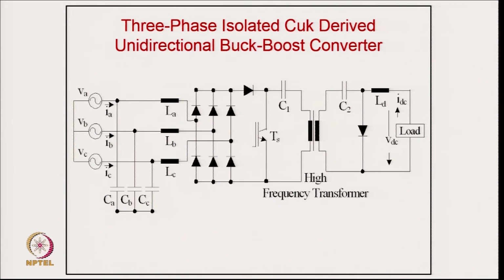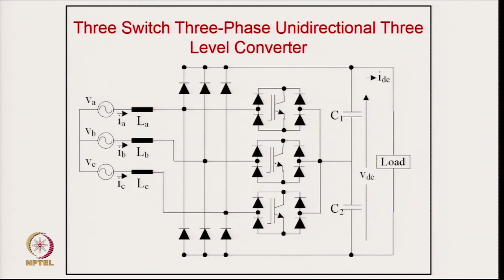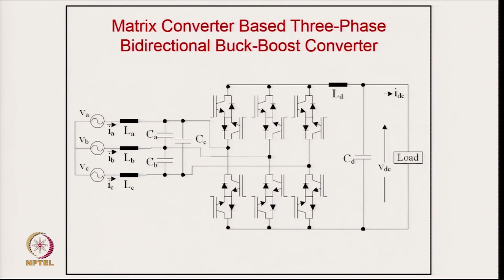And this is similar, after which you have of course the LC filter and a high frequency Cuk converter at the output, operating in DCM, typically for a power factor correction converter with isolation also. And of course, this is 3 level; you can have a multilevel circuit here also for improving the power quality on the supply side and having a boosting operation with the help of the 3 switch bidirectional switch. This is the bidirectional switch similar to what we discussed for your Vienna rectifier, but the number of levels is increased in this case.